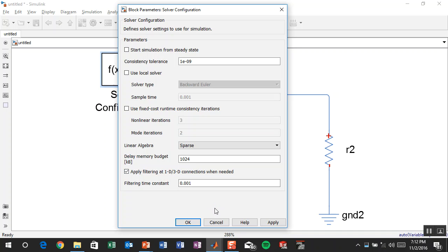But I think you'll find once you start using it, it really helps because, like I was saying a little bit ago, with different physical systems, you might have an electrical system that's really slow. It has RLC time constants that are big. Maybe it's some power circuit, and it just doesn't move that fast. You don't want to solve that at a microsecond scale.